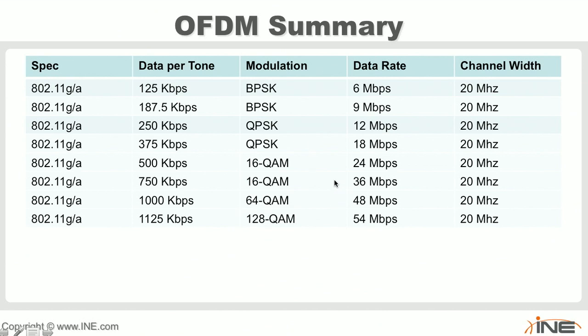As I move away from the center of that client, I can't necessarily hear as much data in the same amount of time. Okay, I can't necessarily do the same or understand the same modulation types or same encoding mechanisms. Because of that, the industry came up with something early on called dynamic rate shifting.